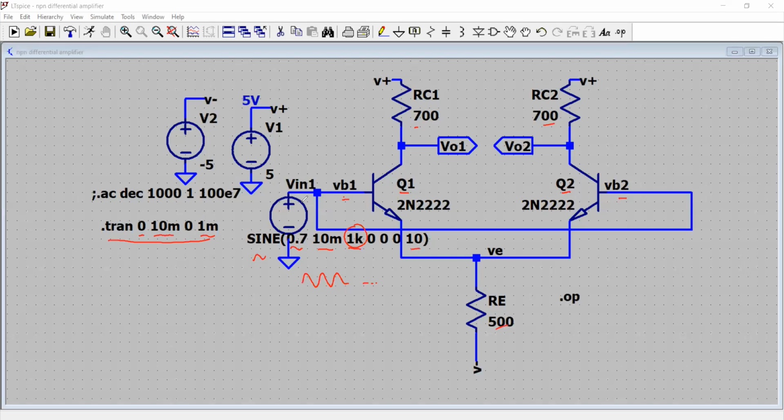What I am going to show you is, if I am applying a signal common to both the inputs of the differential amplifier. For example, here, the two inputs are shorted, and I am applying a common signal, V in, and the output would be gain times VID. So since the signals at the V1 and V2 are same, the difference VID is 0, therefore ideally I should have 0 output at the output terminals, and that's precisely what we are going to do. Now let us run that analysis.